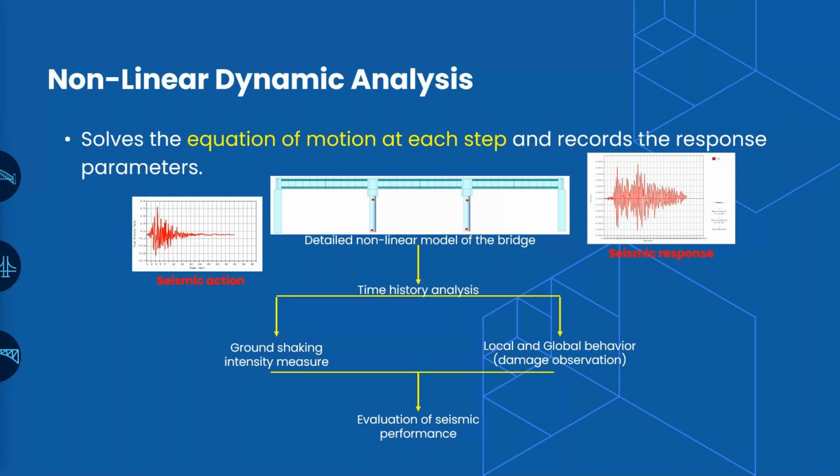Moreover, pushover analysis is valid mostly for the regular type of bridges, wherein the first mode or the fundamental mode is governing with the highest amount of mass participation, which is generally over 70-75% of the mass participation. In such a structure, pushover analysis could be considered as valid. However, for some complex bridges, complex structures wherein there is coupling of modes, the pushover analysis is not completely valid, or it is not recommended to use it. And hence, there is this need of nonlinear time history analysis or nonlinear dynamic analysis, so to say.